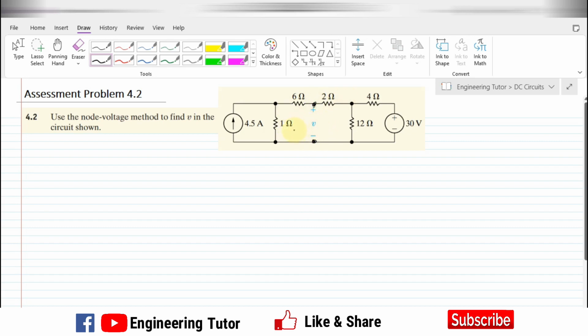In the node voltage method we have several steps, and the first of those steps is to identify the number of nodes which are available in this circuit. So how many nodes do we have here in this circuit? Identifying them, the first node here is this one. Let us call it node 1. The second node here we have is this one. This is node number 2, and the third node, again this one, where all the branches are connected together. This is node number 3.